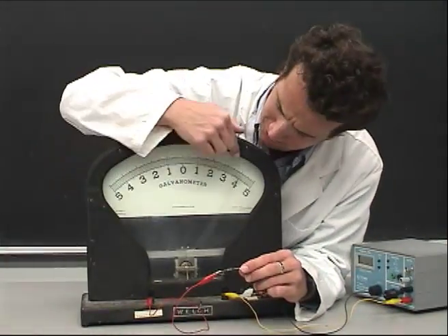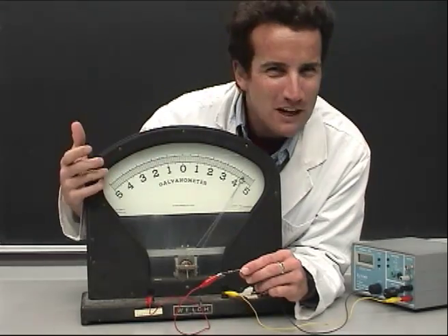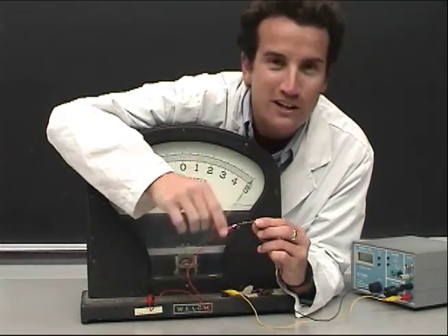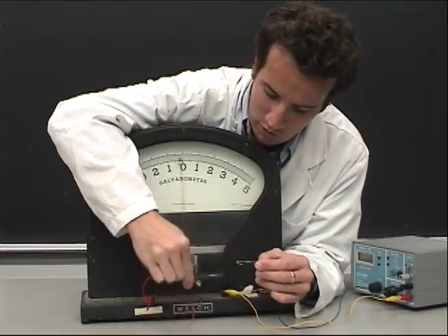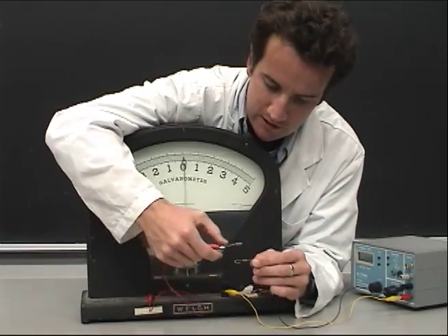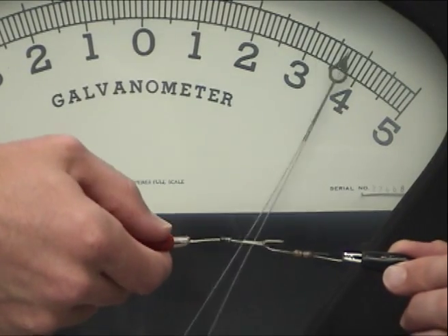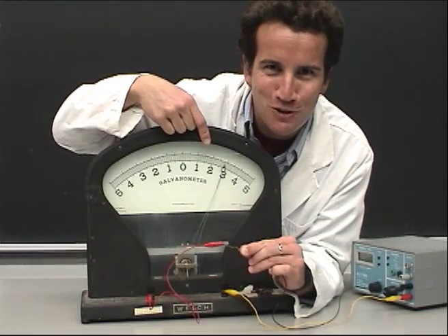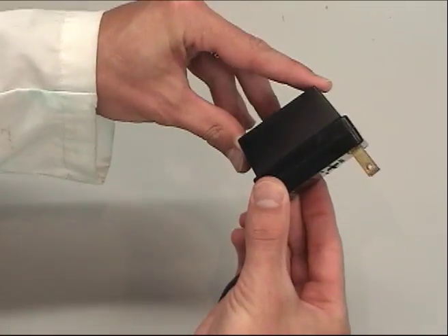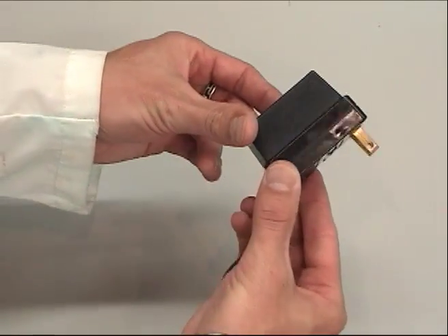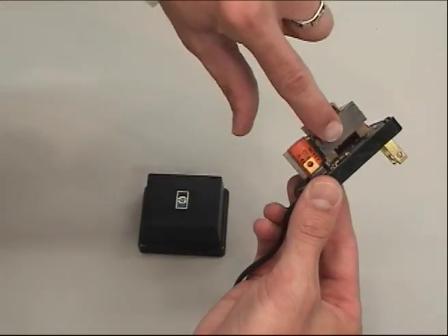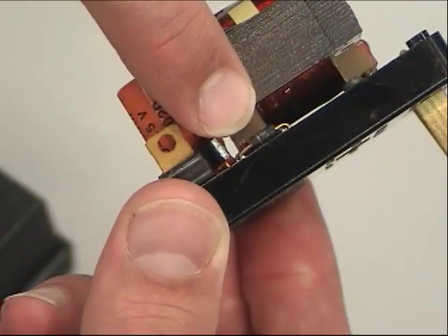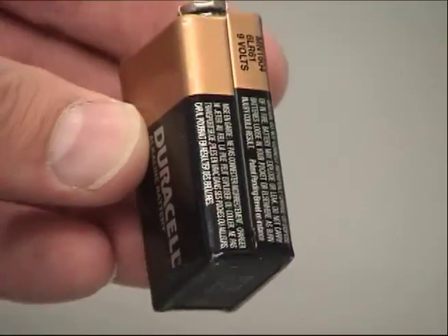Here I've set up an alternating current, a current that goes backwards and forwards, and the resistor handles it just perfectly. But when I hook a diode to the circuit, watch what happens. It only lets the positive current go through. For this reason, diodes are often found inside of AC-DC converters like this one. They help to turn alternating currents into direct currents, make them act more like batteries.